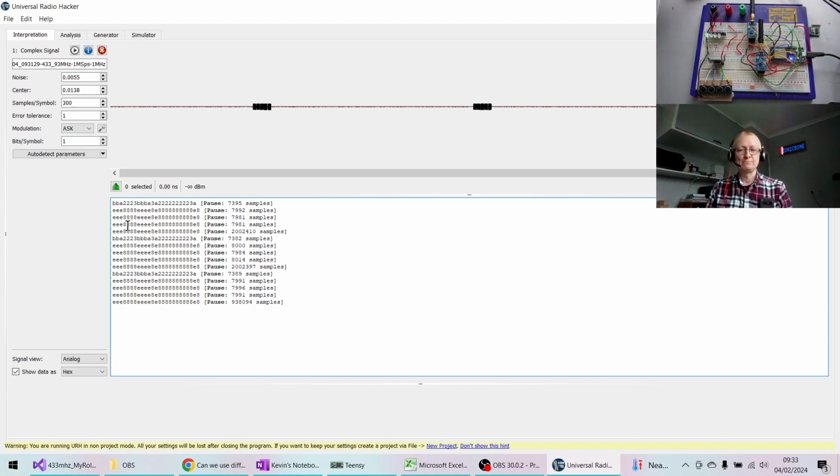And what I pick up from my tests at least, and I've only got 4 of these chips, is that if the unique code is a letter, then it's an E on this rolling part, and if it's a number, then it's an 8. So we should be able to manipulate that during the RollJam experience, and it's worth noting for any vulnerabilities in my project of how that might be computed, let's say, by a hacker.